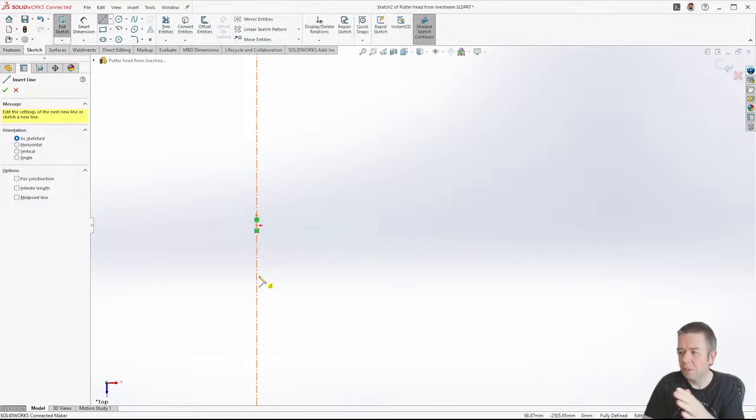So whatever I decide to do to make the geometry of the half I actually draw look great, the thing will be symmetrical. So at least the left-right center of mass necessarily will be in that mirrored center line, and then all we have to do is worry about the vertical center of mass and the front to back center of mass.